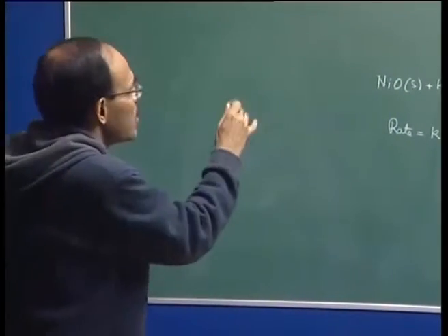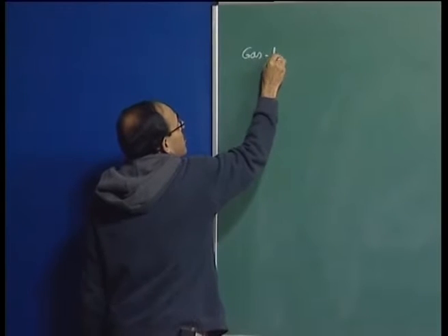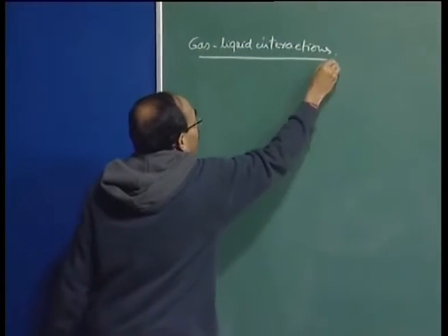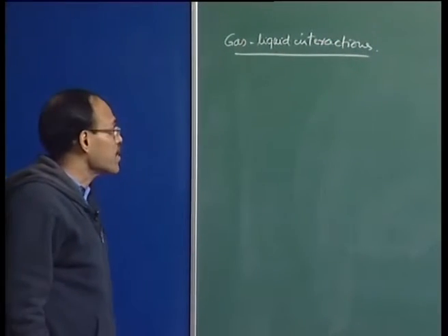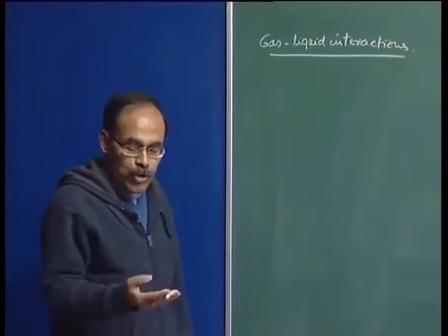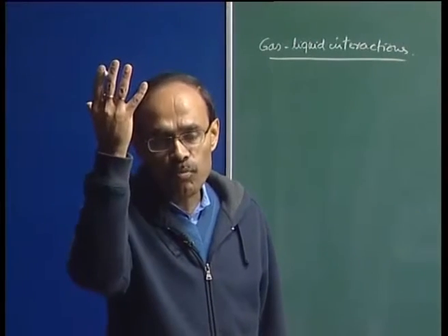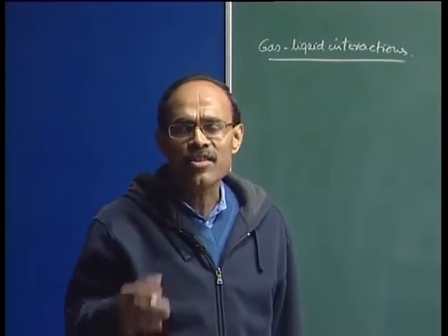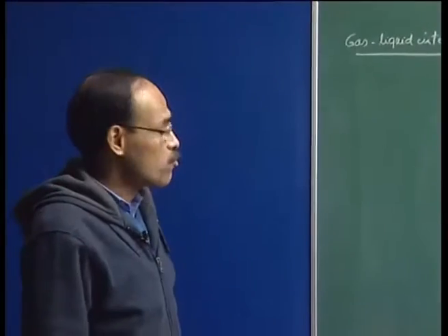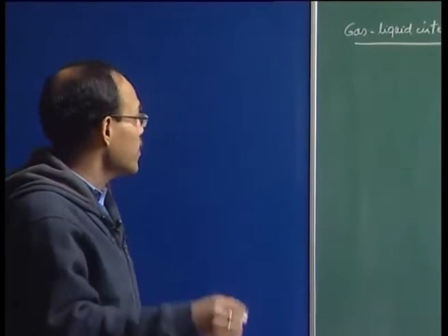Now, very briefly, one more additional topic of quite importance to us is gas liquid interactions. I will discuss this later on in the context of secondary steel making, but this is a topic which goes beyond all this and is of prime fundamental importance to us. When you look at oxygen steel making, we have reacting gases, oxygen being blown into molten metal. We talk of argon stirred ladle, where argon is blown into the ladle. In the tundish also we have gas injection, and in the mold also. Everywhere there is gas liquid interaction, a subject very close to the heart of steel makers, and we have to have adequate background to quantitatively tackle the multi-phase nature of steel flows, particularly in gas agitated systems.